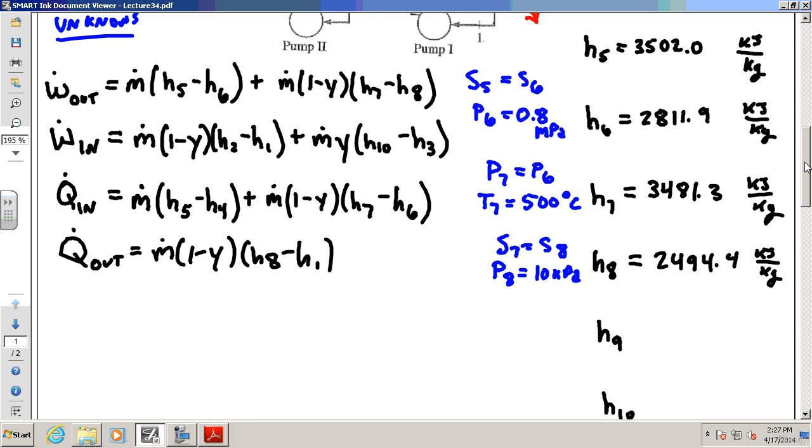And I'm glad you brought that up because now it's time to talk about writing a real equation that we're going to use. These are good. They're going to simplify now. Help me with this. We know we produce a net amount of work of 80 megawatts. Anytime I see a mega, I like to convert to a kilo because I know most of our units are going to be in kilowatts. So we really produce 80,000 kilowatts.